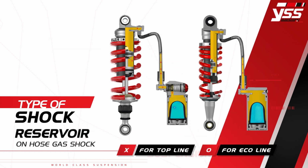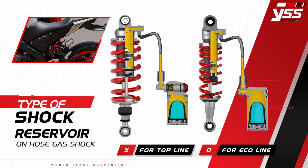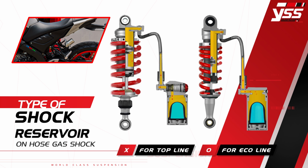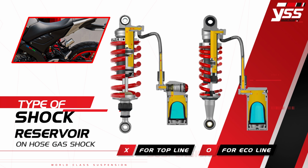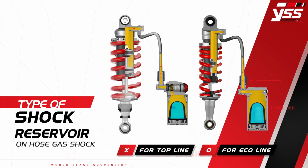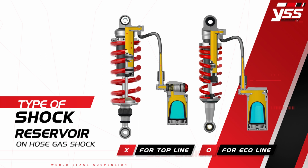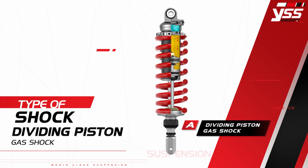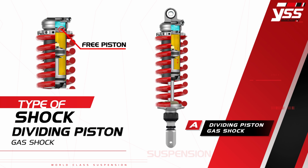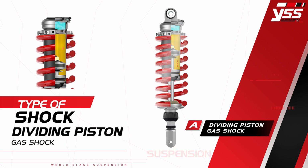Reservoir on hose gas shock, X in top line and O in eco line. This gas shock absorber has a hose with a piggyback. The reservoir can be installed in an unobstructed area to solve the problem of some vehicles which have less space to install a shock absorber. This shock absorber can adjust both rebound and compression. Dividing piston gas shock, A. This shock absorber has oil and gas separated by a free piston and can adjust rebound.